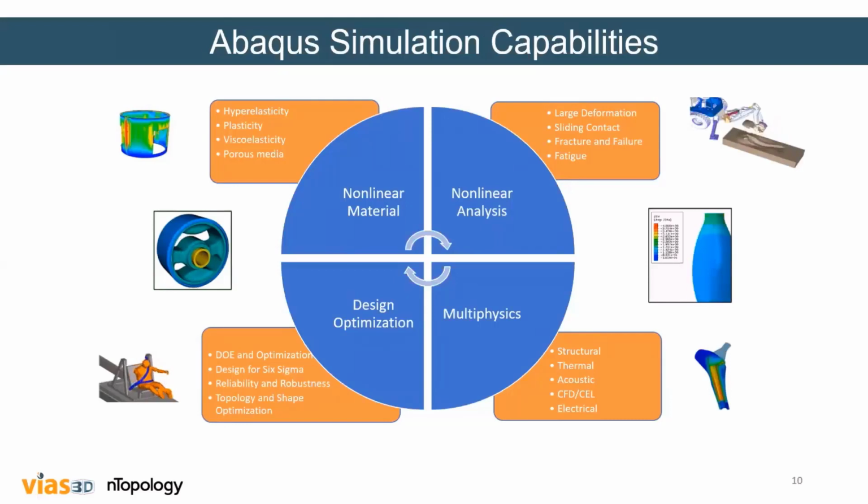So these are the main aspects of any sort of Abaqus structural simulation. I would say structural or non-structural, it can be fluid and others, but this example is more for structural. So nonlinear material property, any sort of nonlinear analysis. Material models in Abaqus, there are standard material models, but then you can also write wrapper codes around the kernel of the software, where we can bring in new material models, and then it interacts with the general framework of the software.